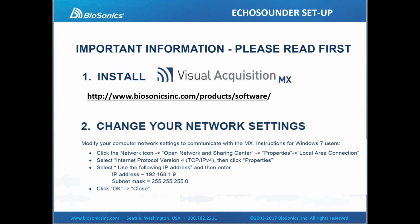When we're setting up the MX Echosounder, as soon as you open the box of the new system, this piece of paper is going to be right on top of the box. Important information, read first. Step 1, you've got to install Visual Acquisition. So go to the BioSonics website and download that. Make sure we have that on our computer. And we're also going to need to make a change in our network settings. So those instructions are provided clearly here. We're going to go in and make that quick change. And this allows you to communicate with the Echosounder via the included Ethernet cable to your laptop computer.